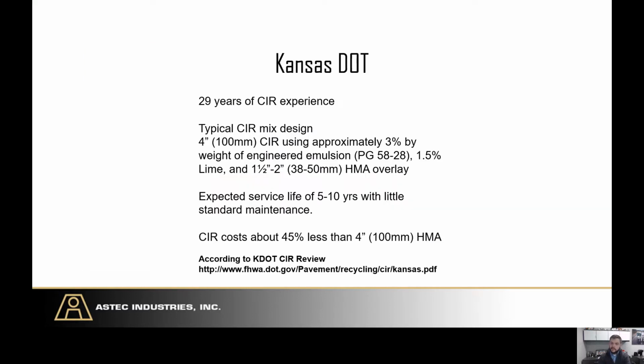Just some experiences out there. Kansas DOT, they've got 29 years, well now even more from when this was captured, but a lot of cold in place recycle experience out there. And you can see their typical mix design. It does include some lime. They expect a service life of 5 to 10 years with little standard maintenance. And the biggest thing is it costs about 45% less than 4 inches of hot mix.